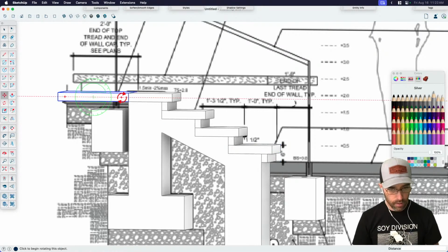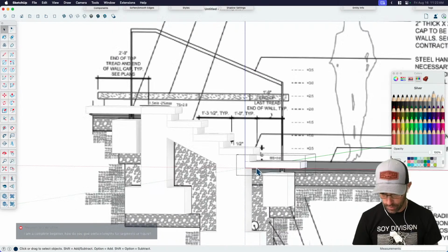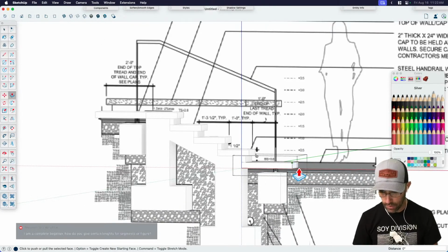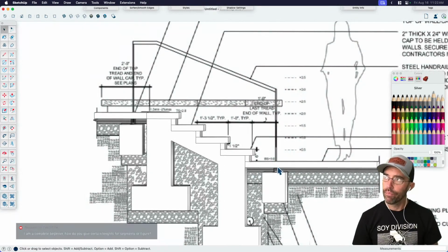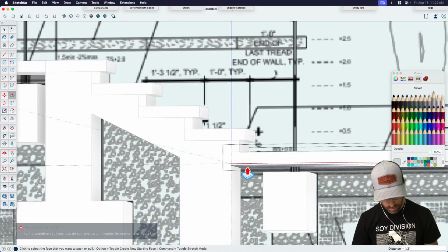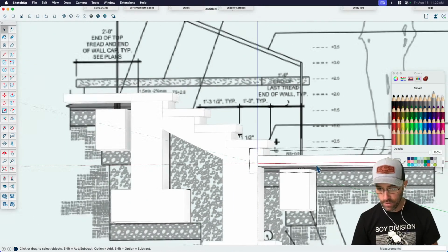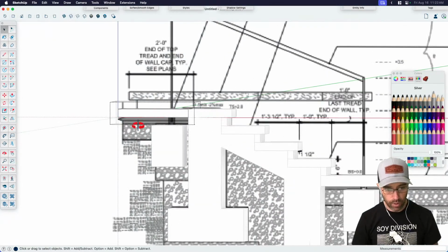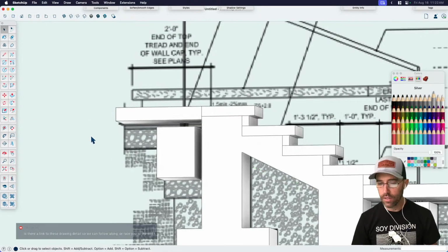And then, we talked about this last time too. For those that didn't see that stream, that's okay, because again, this is a little bit different. But something we talked about is components. When do you make a component, or when do you make it a group? And I think that's going to be tough, because if you make it a component and you copy it a bunch of times and then you find that you need it unique, then all of a sudden it's going to be a lot of work.